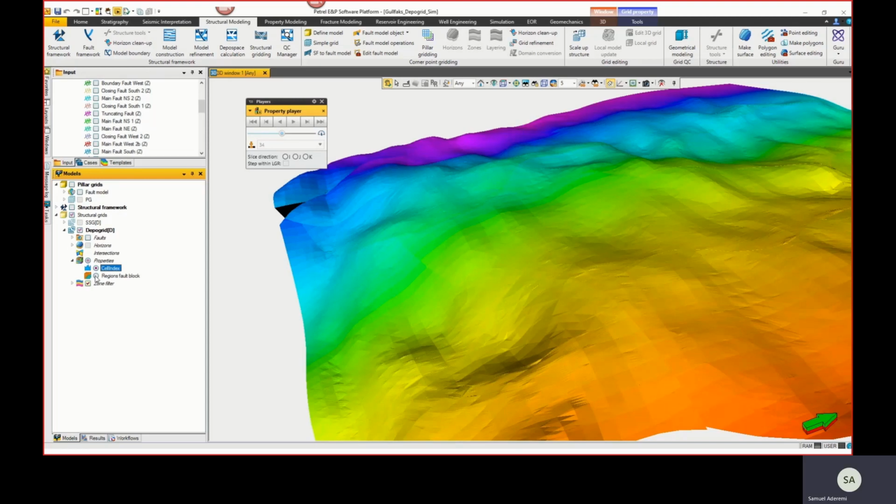They are cut cells because the fault that has gone through that cell has split it into 2 or 3. All these 2 or 3 cells will end up having the same IJK value. And that is why the IJK value is not unique. But the cell index gives that uniqueness that we require.